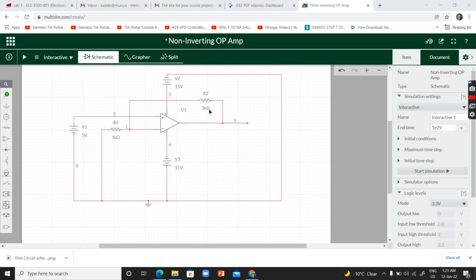All right, so I've connected this feedback resistor to this negative terminal over here. And if you can recall the classes for the gain, I want you to think in your mind what will be the gain of this op amp with the formula, right? For these type of non-inverting amplifiers. So just think about it and what should be your gain. So the answer for the gain for this circuit is going to be 2.